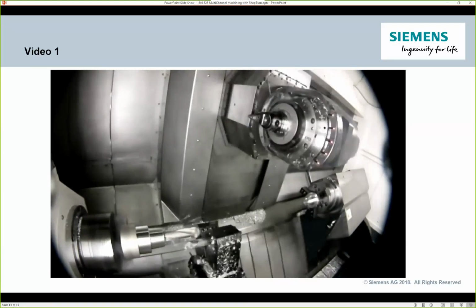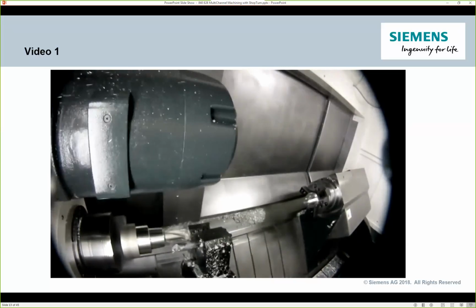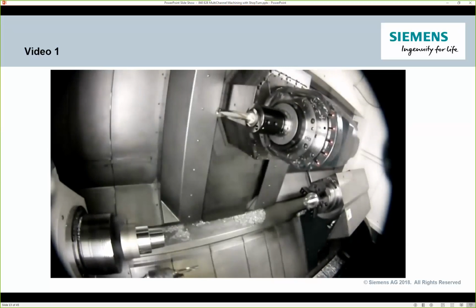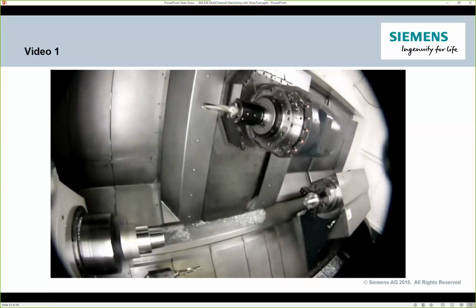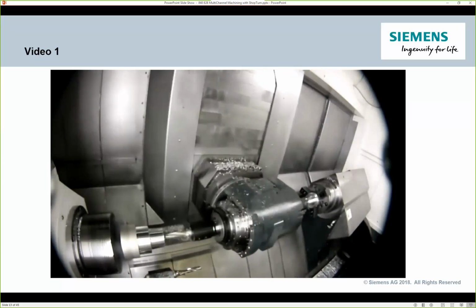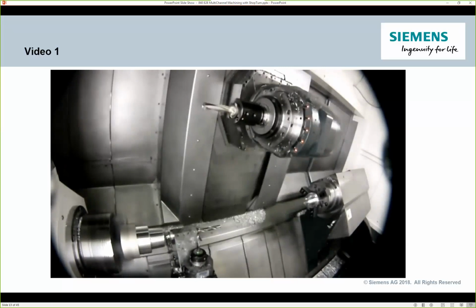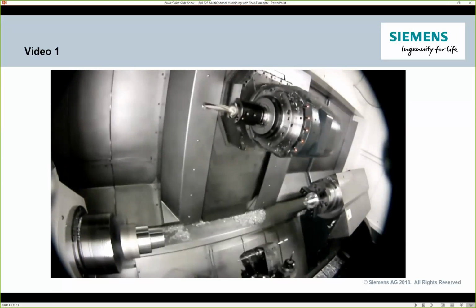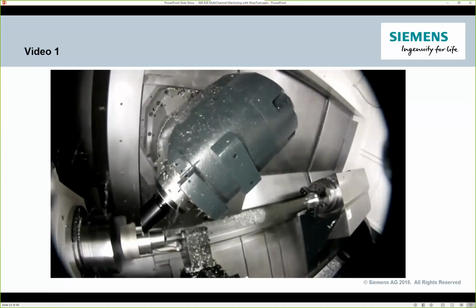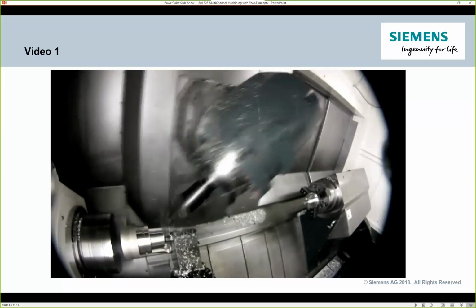I can have one channel jump to the other spindle. So here, for whatever reasons, tooling configurations or whatnot, we decided to let the lower turret do the drilling on the main spindle. And now we're going to come in with the upper milling spindle or upper turret, which we're going to refer to it as, and start to do more work. So you can get really versatile, and it gives you a lot of configurations or capabilities when you're moving around and methodizing or processing a part. Here we're doing tasks simultaneously on the same spindle.